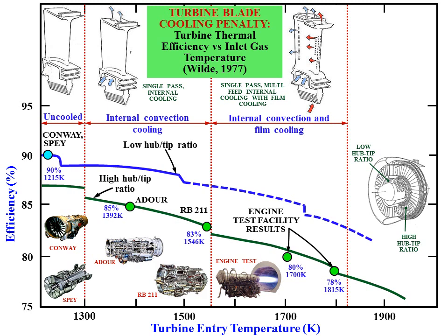So you can see that if we use more advanced cooling processes for the turbine blade, which involve more cooling air, the efficiency reduces. Although the turbine entry temperature that can be withstood by the blade increases, the efficiency keeps reducing.